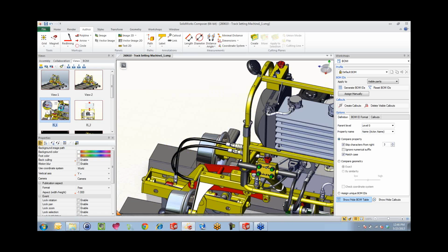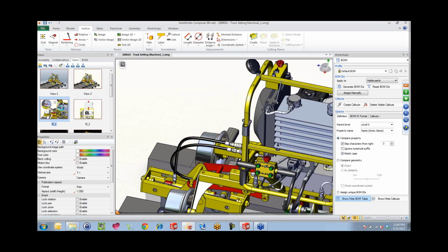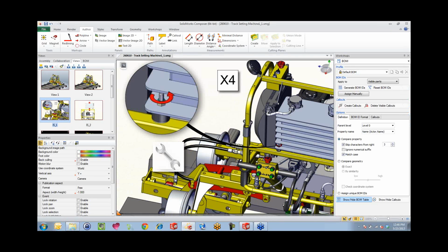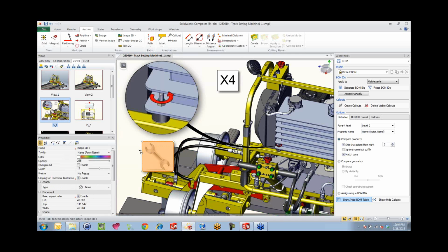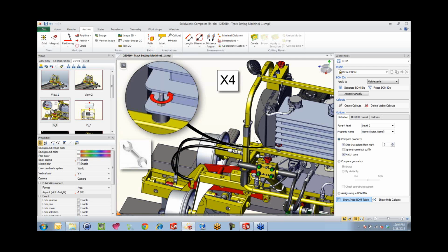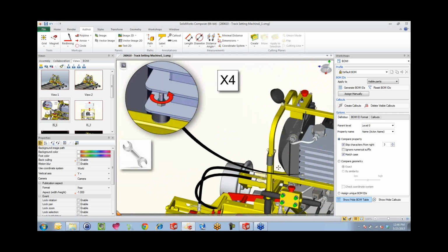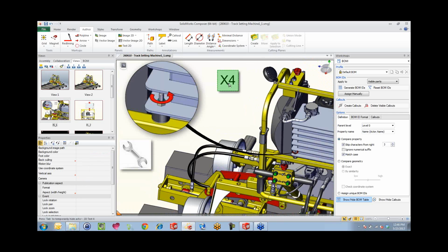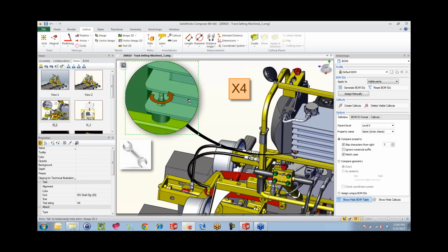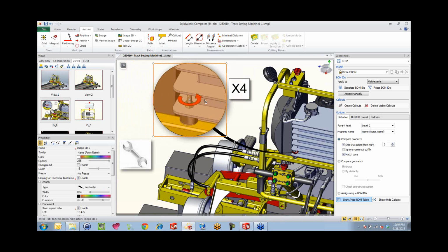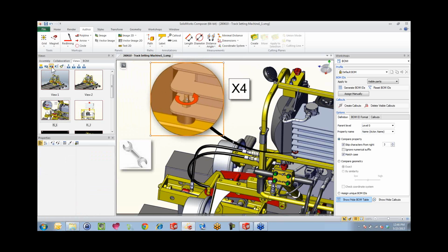picture we created there with the turn arrow and the magnifying glass and that kind of stuff. Now where we added these other components in, maybe this picture, maybe we don't want it to overlay something else. We could start moving that around. I could also, at this point, do SolidWorks commands like hold down my control and my middle mouse button, and you see how I can move the assembly around. So even though I started my process earlier, I have the power to readjust all these things to the way I like it, and again, I just go in and hit update.